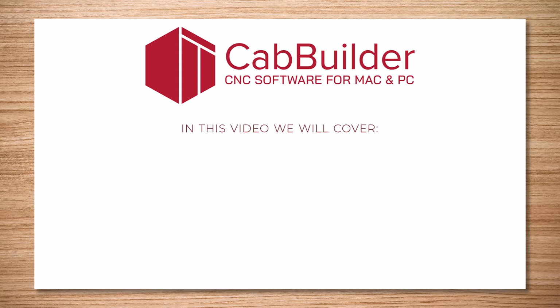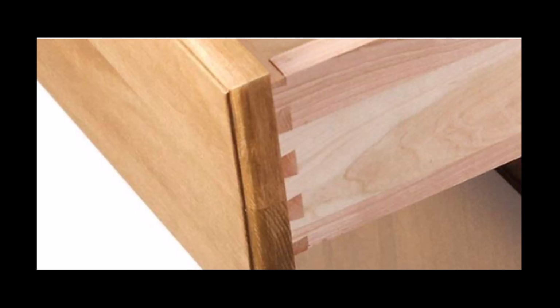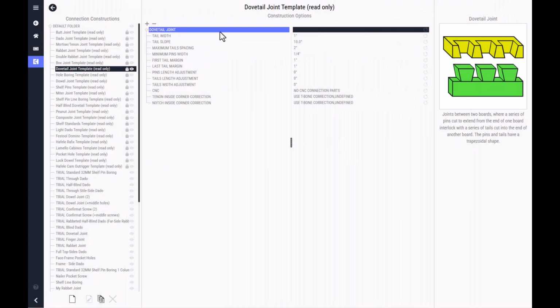In this video, we will take a look at how to create and configure a dovetail joint connection construction in CAD Builder. The dovetail joint uses interlocking pins and tails to join two parts together. CAD Builder provides settings for the dovetail size, pattern layout, fit adjustments, and inside corner treatment. Let's see how this works.